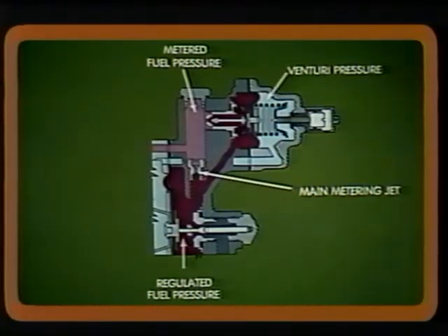When there is sufficient airflow through the engine to demand additional fuel, both the metered fuel pressure and the Venturi pressure will be sufficient to open the valve. This allows additional fuel to flow from the regulated fuel pressure chamber to the discharge nozzle.